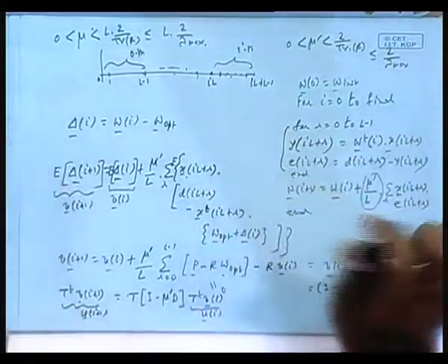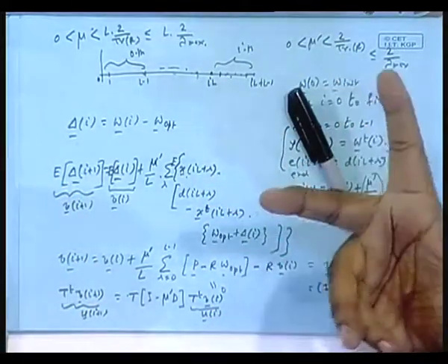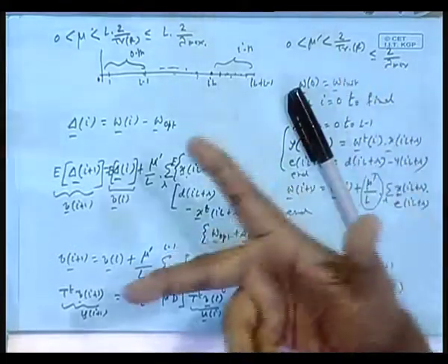Now people have done again, a lot of research has gone into LMS. They then try to do the same mean square analysis, which we did at length for 3-4 classes. You remember, no? We found out the mean square error in the steady state, that had one extra component called excess mean square error that was evaluated in terms of weight error covariance matrix, K n, rather K prime n. We found out the dynamics of K prime n under some assumption and all that. From that we evaluated that excess mean square and then misadjustment. Same thing can be done here, people have done, but no need to repeat, more or less steps are common. So, we will not go on doing it for all elements, because this just gives you a test. I will do now something which is more DSP, that is its implementation.